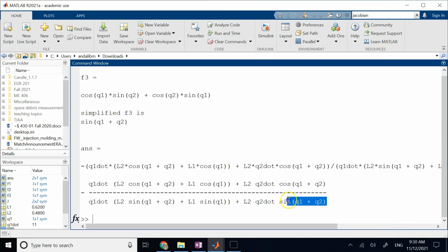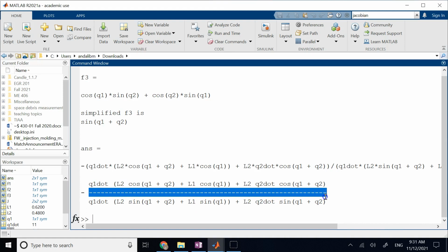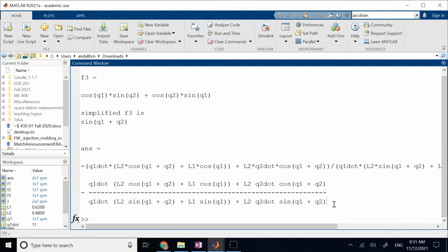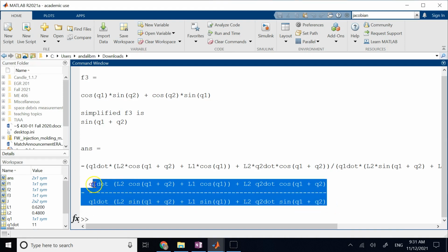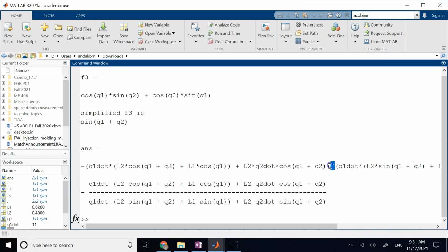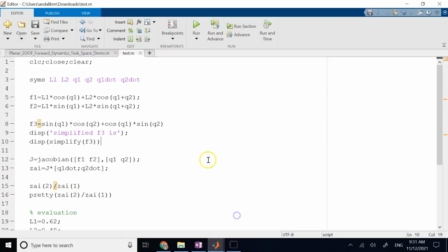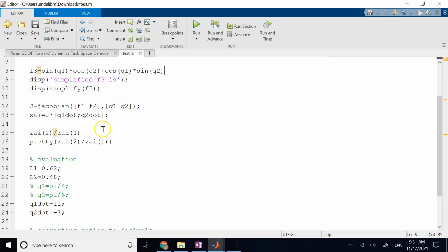The other one, it actually writes it like a division for you by adding all of these dashed lines to be like the division line for you. So you see this is much more readable than this long line. And the longer they are, the more terms you have in denominator and numerator. Typically, this command pretty can make life a lot easier on you. Okay, so that's another thing that I wanted to emphasize for you, the command pretty.